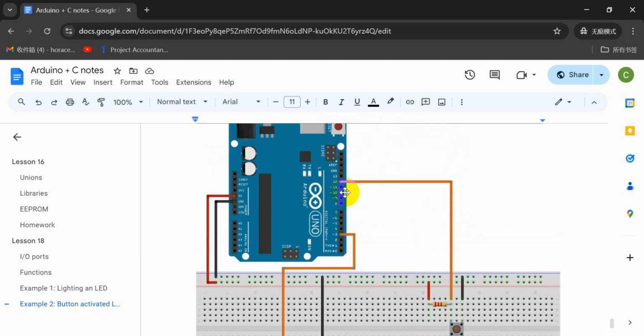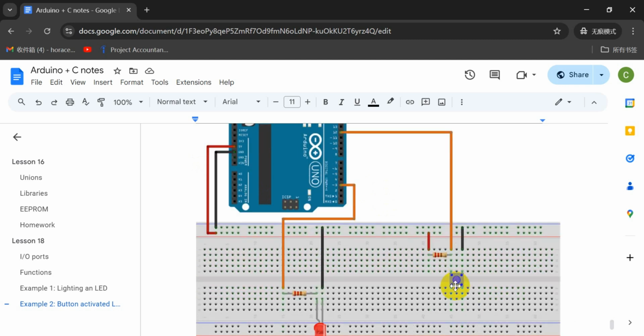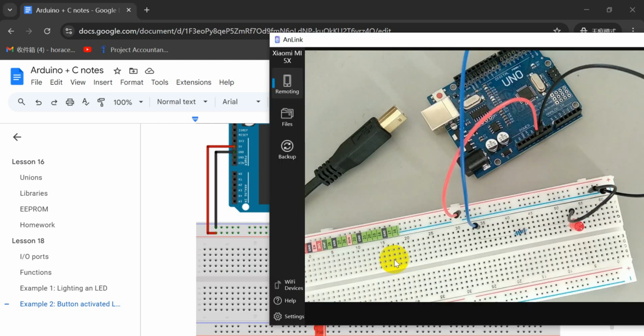And that's because in each port there's a little bit of resistance, and so if it's going to ground, it would have less resistance. So when the button is pressed, the electricity goes through the ground. So when the button is pressed, it becomes 0, and if it's not pressed, it's 1. So let's build this.